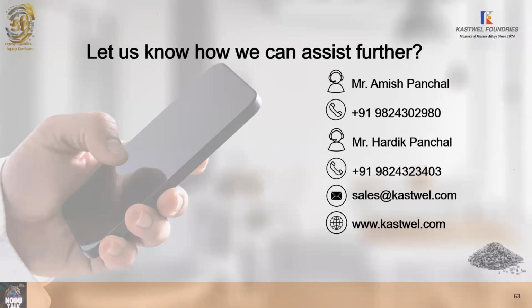The chunky graphite which you see in the casting is probably due to higher cerium content. I do not know what is the section thickness of the casting. We have given you a table towards the end in which, depending upon the wall thickness, the recommended level of free cerium is indicated. So if you can keep the cerium low, or for ferrosilicon magnesium treatment use half ferrosilicon without cerium and half ferrosilicon with rare earth cerium, that will keep the total cerium in the casting low and therefore avoid the formation of chunky graphite.